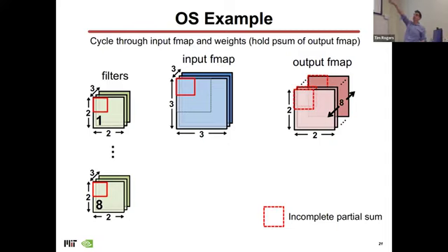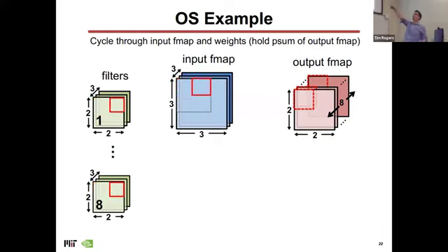We're just taking a small piece of each individual filter's channel, which comes in to do the MAC associated with this small part of the weights right now. And then in the next cycle, we'll do a different part of the input FMAP. So you're flowing the input FMAPs into this processing array, and we're going to broadcast or read a different subset of those weights that are being broadcast to everybody. And we're going to keep the output stationary. Okay, we're going to keep it all local to the PEs.